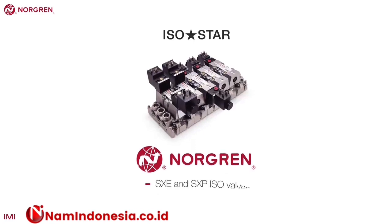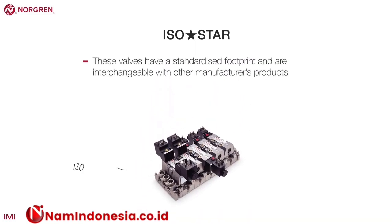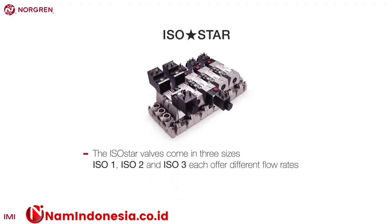ISOstar are Norgren's range of SXE and SXP ISO valves. The ISO standard means these valves have a standardized footprint and are interchangeable with other manufacturers' products. It's only the footprint that is standardized, though, and the operating parameters of the valve are not covered. The ISOstar valves come in 3 sizes. ISO 1, 2, and 3 each offer different flow rates. Size 4 is available in the UM22000 series.